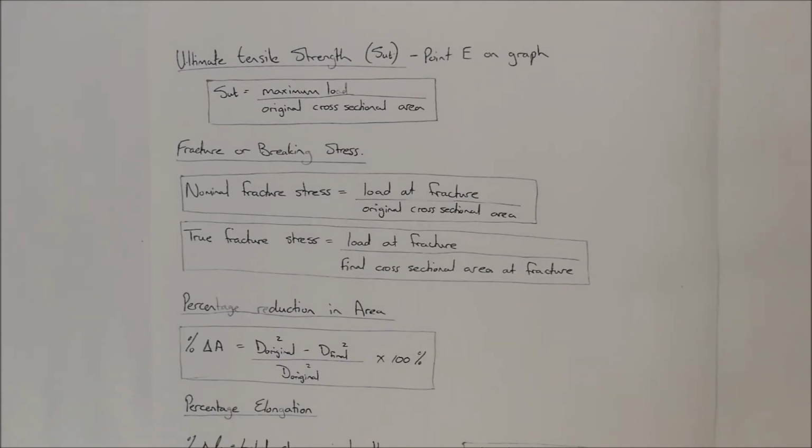And so we are able to identify what the load was at the fracture, or just before fracture occurred. And with that we would also have been able to identify the cross-sectional area if we had measured it. Obviously it makes it very difficult when you get to a very critical point where you just can't go past it and you could actually snap it before measuring the cross-sectional area.